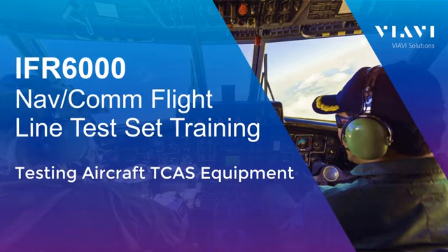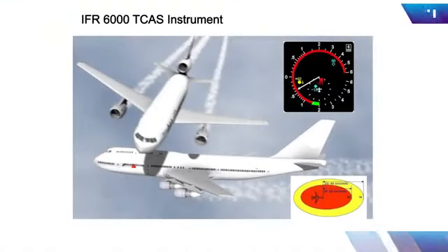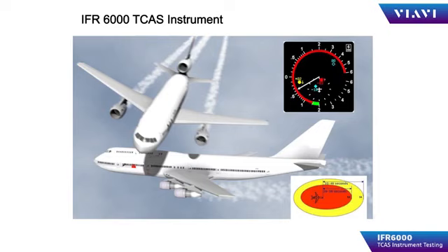In this video, we'll describe the TCAS testing using the IFR6000 test set. The IFR6000 can generate a target for testing the performance of TCAS systems and parametrically evaluate the interrogation signal for items like frequency, power, and data content.